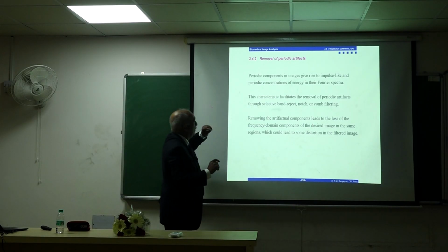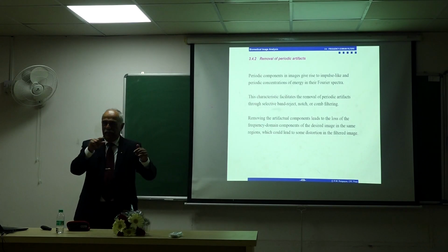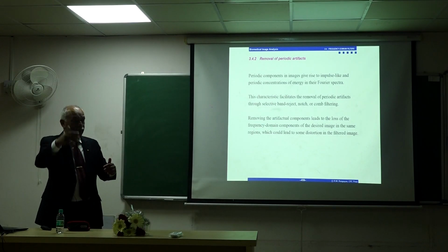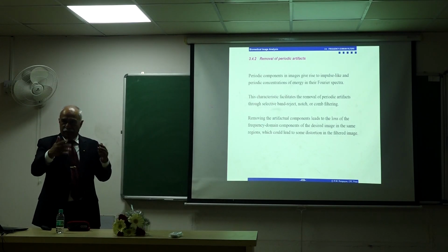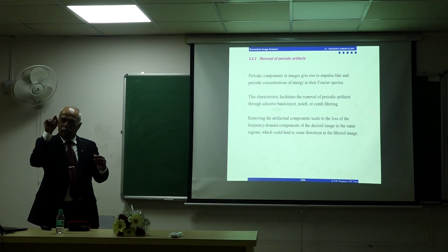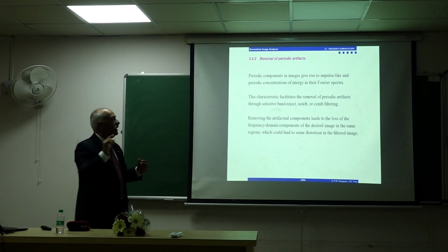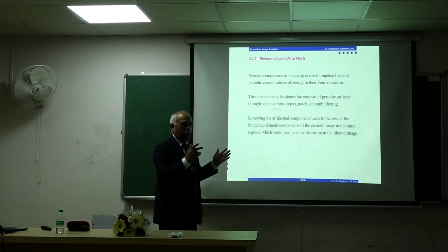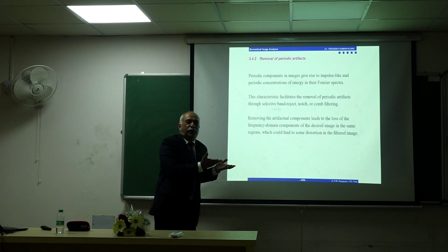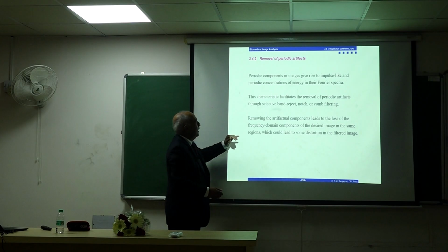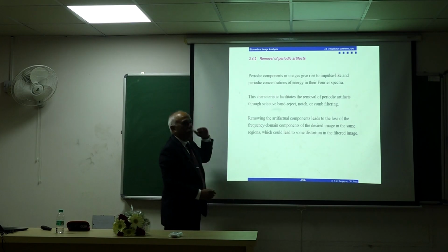So this facilitates removal of periodic artifacts if you know what the period is, or you examine the spectrum of the distorted image, and if you see points of high intensity, that indicates periodic artifact, and that should be visible in the image too. So you remove these artifacts.